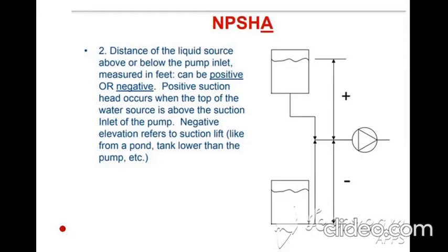In the diagram the circle indicates the pump, and both boxes are fluid sources, but the upper box is located above the pump, so it has positive head, and here head means the height from the upper level of liquid to the pump inlet. If that height or head is proper, then it will cover the pressure drop created during the design of the pump, and then cavitation will not occur.